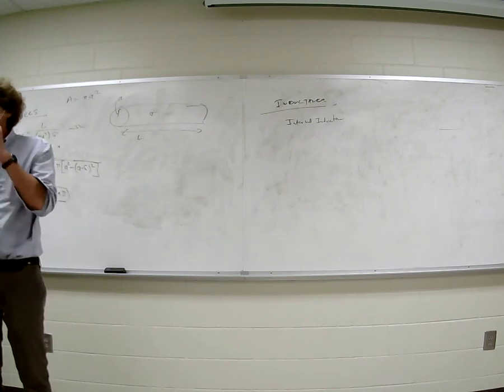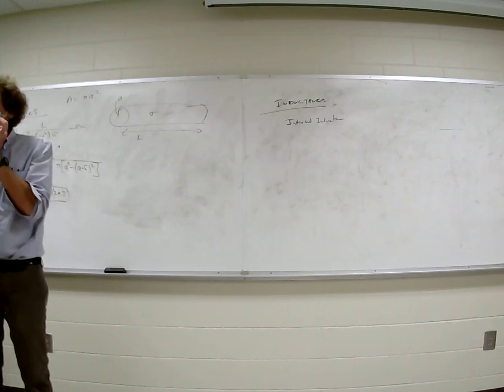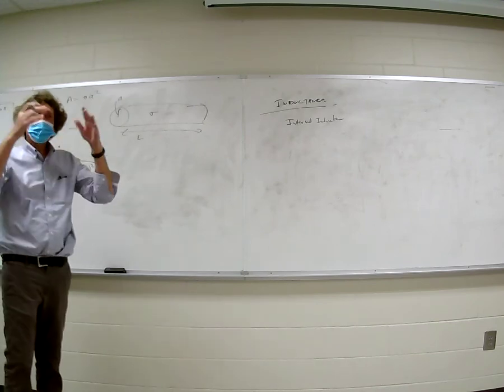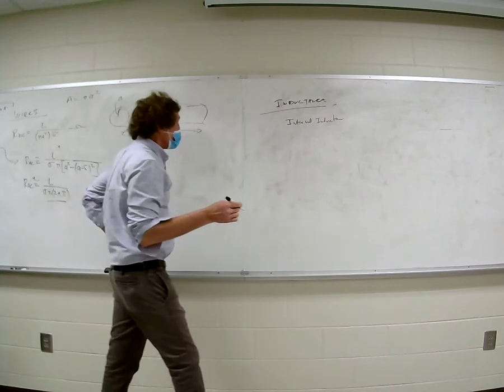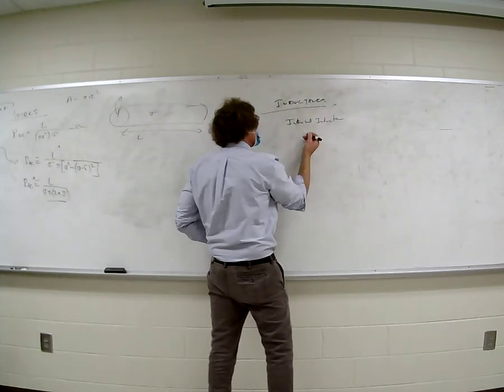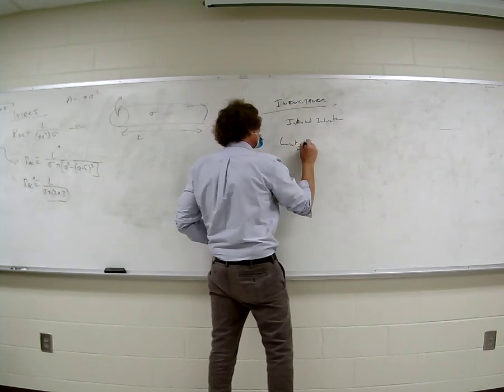It is if they're parallel, like transmission lines, like extension cords. Then that inductance will be significant and may be the dominant. But generally, the magnetic energy outside the core of the wire is where all the energy is. So inside the wire, this is internal inductance. We take a look at L internal, and this would be for DC.